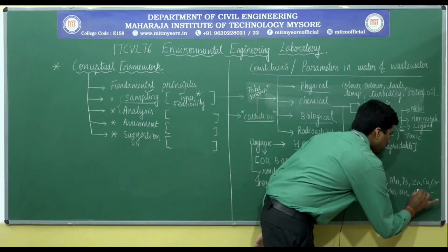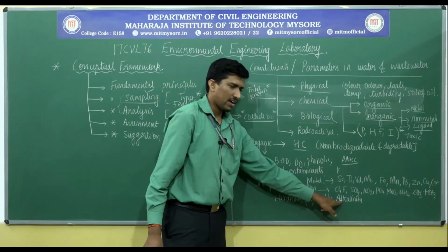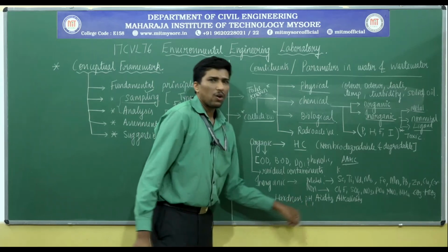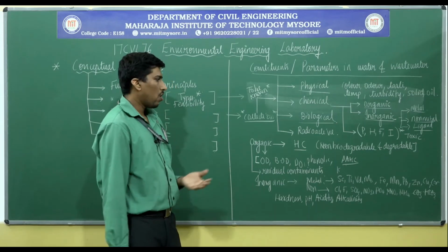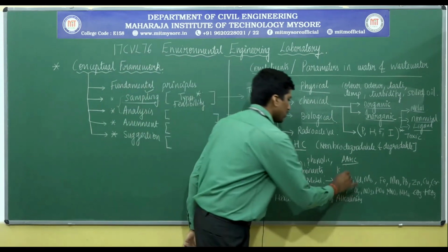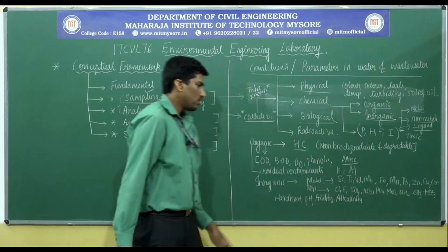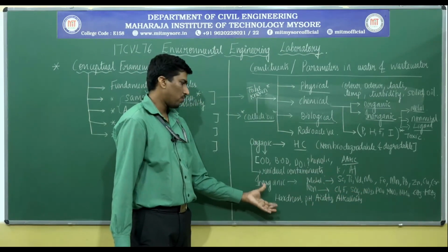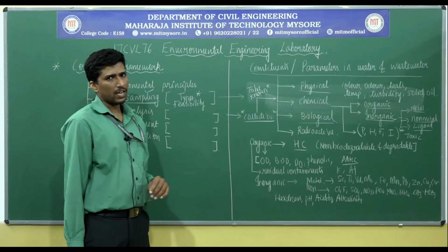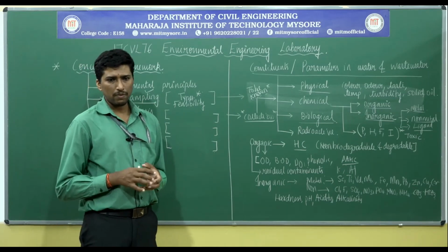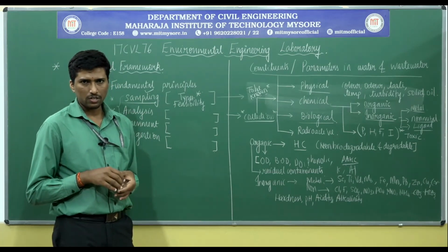For this I can also mention carbonate as well as bicarbonate, because they are the major driving factors for acidity and alkalinity along with the pH. Next we have the determination of the chlorine optimum dosage, and in addition to this we also have the aluminum content. So on we have. Majorly we have to go for checking the quality of the water as well as the wastewater. There are different types of contaminants. To list them, there may be 45,000 compounds present. But all those things we cannot analyze in our laboratory, time is very short.